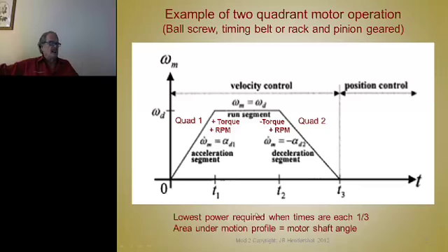So you could go through that angle in those extremes. You come up in 0 time, hit a lower speed, and stop in 0 time. Or you can take the maximum acceleration time and do a triangular move. But the area of the triangle, the area of the rectangle, and the area of the trapezoid, they all have to be equal. And of course, when you accelerate, you overshoot. So you're going to have some settling time there. When you stop, all of a sudden, you've got a big inertial load, you're going to overshoot.